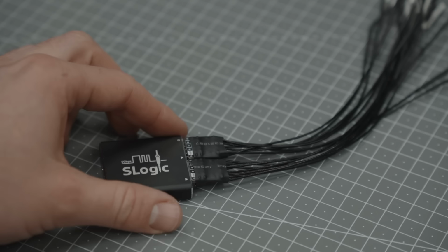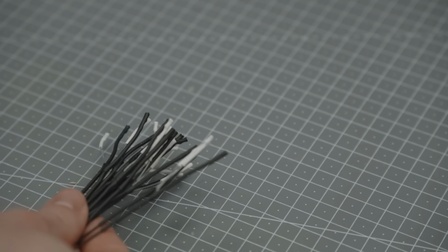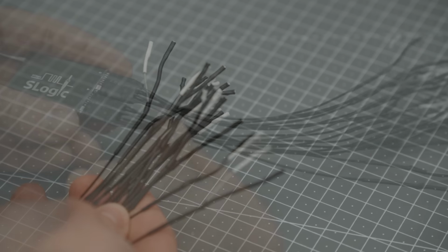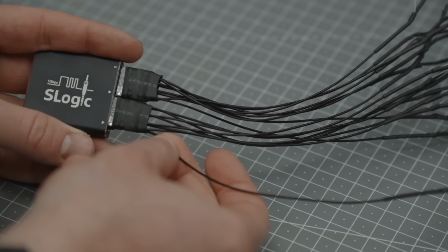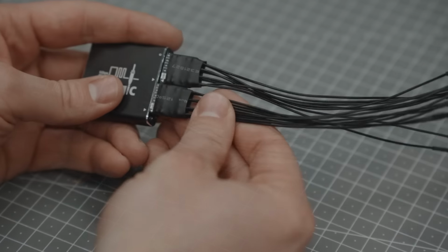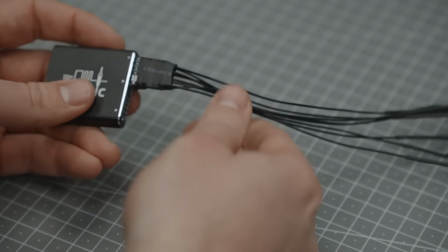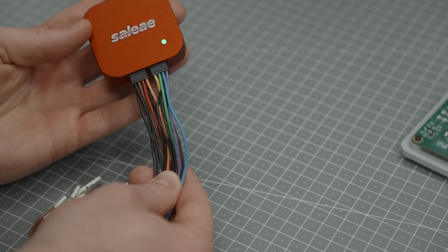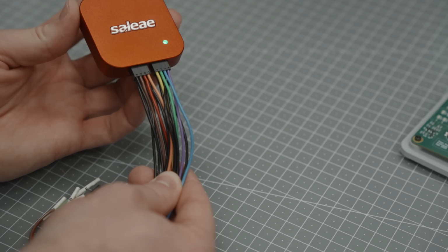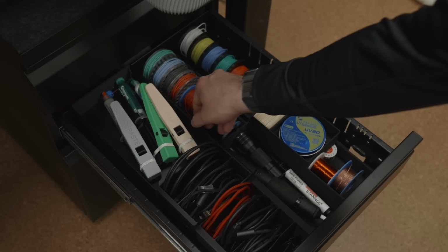Side note, we're now having 16 cables tangling around our workbench with no way to tell which corresponds to what channel, other than tracing it back to the connector. I mean, yes, we can unplug 8 channels, and that's what I did, but with the SAILI all the wires are color-coded to match the channel colors in the software. So I'd probably buy a set of colored heat-shrinking tubing, at least for the common channels 1 to 4 or 1 to 8, that matches the colors of the channels in PulseView.